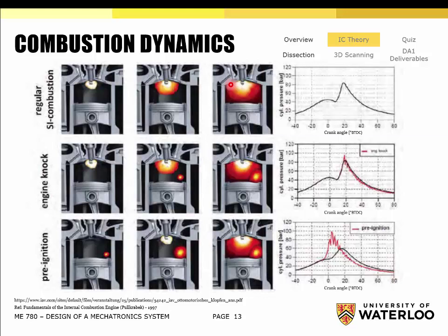Torque is almost directly proportional to the engine displacement, because the amount of air-fuel mixture that you're combusting is proportional to the amount of force that you can put on the pistons. So if you need to produce a lot of torque, you need a larger displacement. They might not be larger in physical size, but generally they have larger displacement, and most of the time that correlates to a larger physical size.